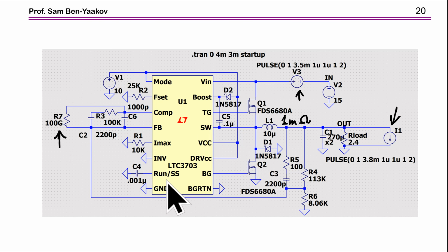Now in this case, this circuit is not compatible with AC analysis, so I cannot run AC analysis. There is a way to get the loop gain, actually in LT-Spice. This is the LT-Spice presentation, which is kind of cumbersome. I'm not doing it. I'm just looking at the time domain responses.